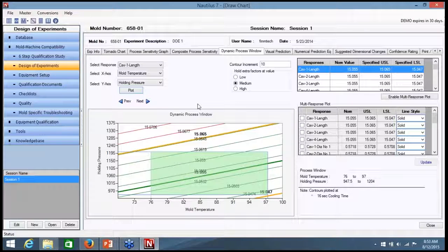The next question is, as far as wall thickness is concerned, where should the gate go? The gate should always be in the thickest section of the part, so that you'll always fill from thick to thin. If you start from the thin area, then the thin area will freeze off faster. You'll never be able to pack out the thick section.